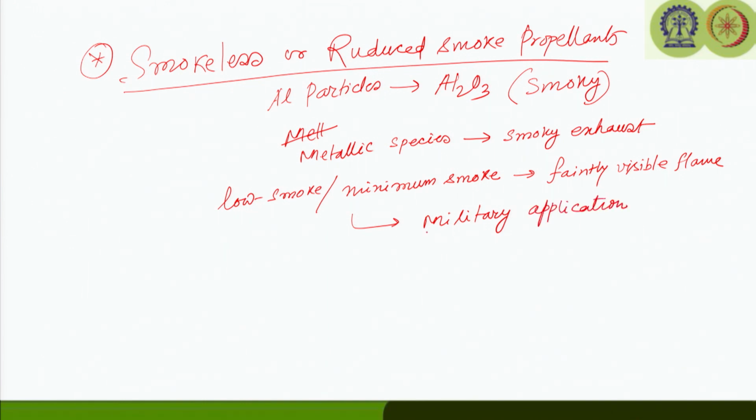This finds applications mainly in military applications, where smokeless exhaust will help dodge the enemy's radar, or it will not be easily detected by the enemy's radar. There are different kinds of oxidizers that have been tried or researched just by looking at how to minimize the exhaust smoke. For example, if we do not use any kind of solid particles within the double base propellant matrix and modify it with some HMX or even RDX, this may actually give very few or even no solid particles in the exhaust. So, we can have DB propellant modified with HMX, and this is going to give us no solid exhaust.